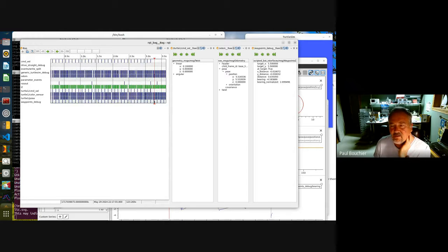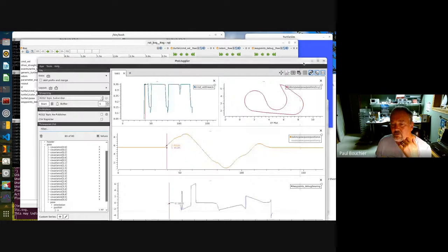and so we're right here. We can go back one message in waypoint debug until we see at target. So at target was false. So we're right at the transition where this at target state transitioned from false to true. So that's where the robot considered it had met its goal. And this happened at, we can see the timeline, and it says it's at 123.164 seconds. So we can now transfer over to